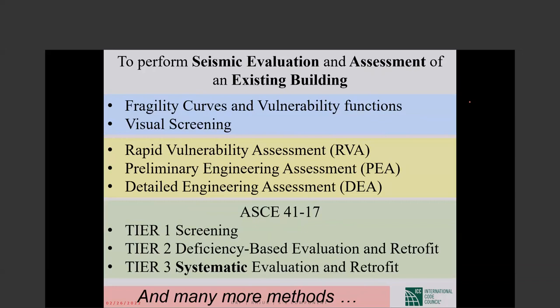You can find many deficiencies and provide some detailing or advice to increase the seismic behavior of that building. The easiest is just to reduce the weight of the building. Some of the floors, some of the slabs, some of the partitions. If you can reduce the weight, it will reduce the demand.